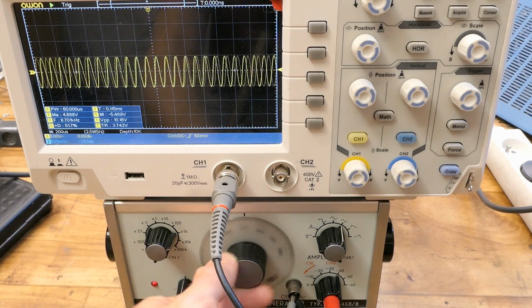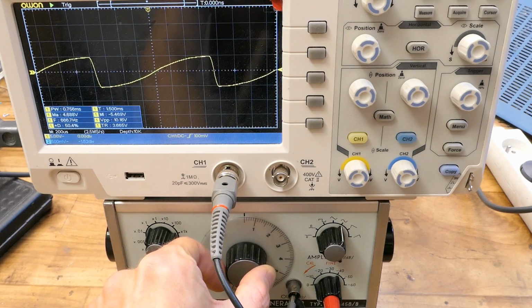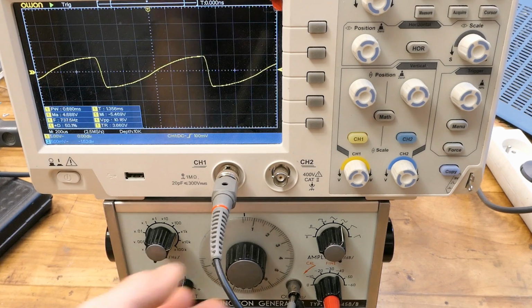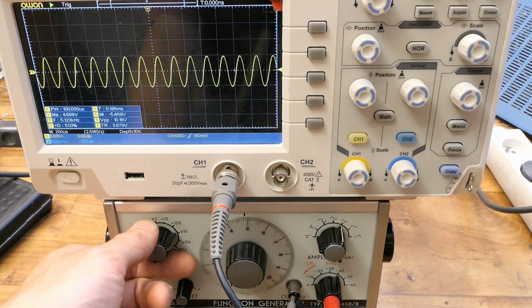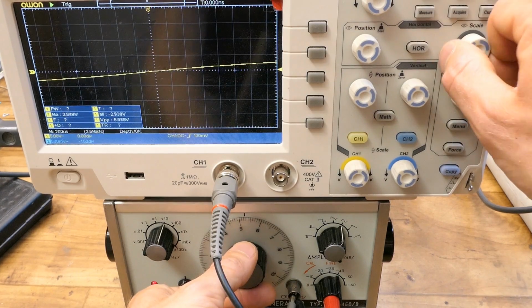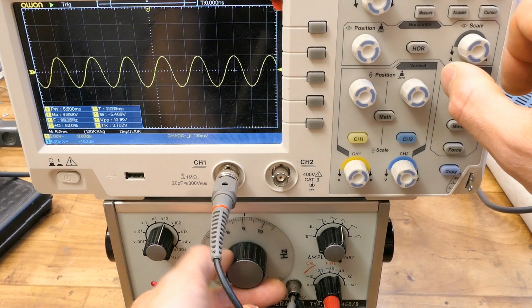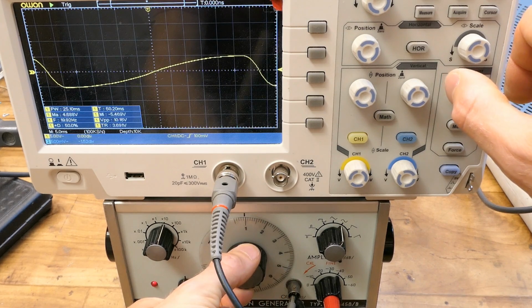The upper part is a nice sine wave, the lower part distorted. And of course in an old device you'd suspect first some capacitors, but this problem is completely frequency independent. It basically happens in the lower range of the knob, no matter if it's like 1 Hz or 100 kHz, so it can't be a capacitor.